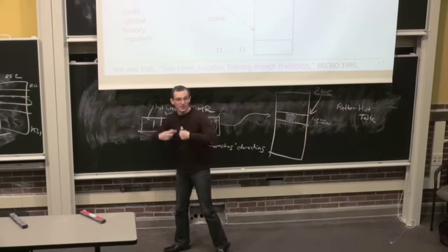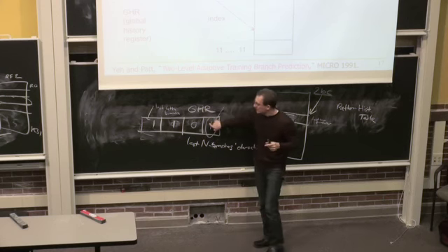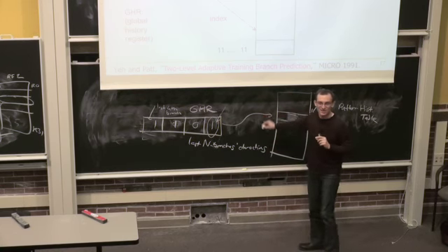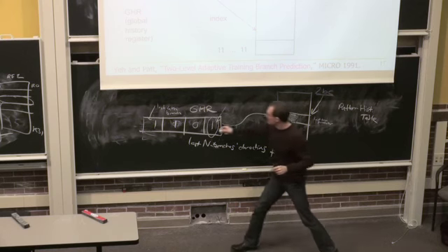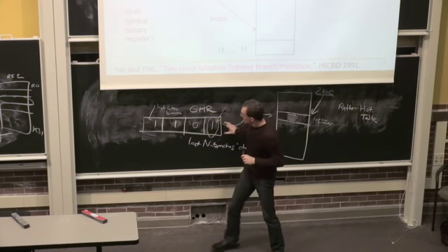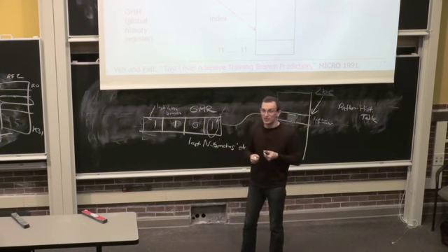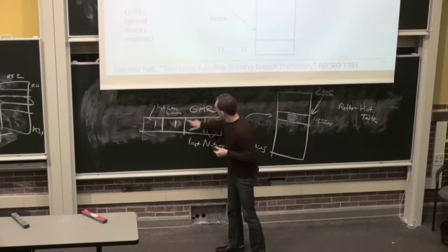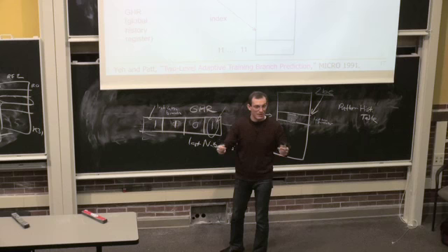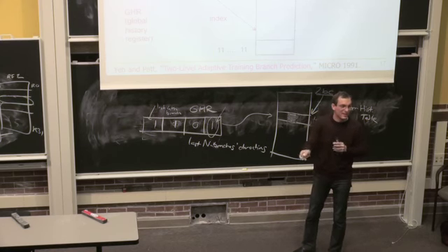As you increase this, now your training time also increases, right? Because if this is only 1 bit, then you can train very quickly, right? You're just looking at 1 of these locations or 2 of these locations. But if this is 16 bits, then you have to see the same pattern, if you will, multiple times to be able to train, to be able to figure out whenever I saw this pattern the last time, or how many times, where did the branch go? Does that make sense? So there is a trade-off.